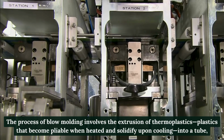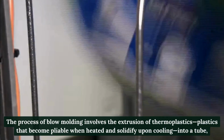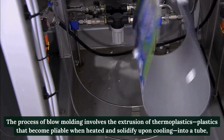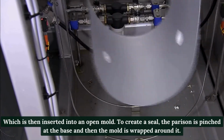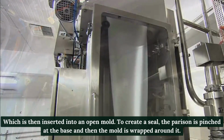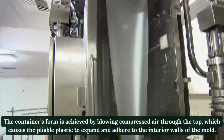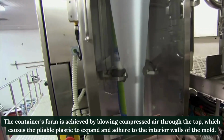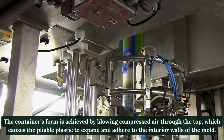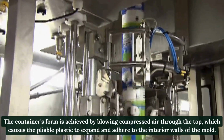The process of blow molding involves the extrusion of thermoplastics, plastics that become pliable when heated and solidify upon cooling, into a tube, which is then inserted into an open mold. To create a seal, the parison is pinched at the base and then the mold is wrapped around it. The container's form is achieved by blowing compressed air through the top, which causes the pliable plastic to expand and adhere to the interior walls of the mold.